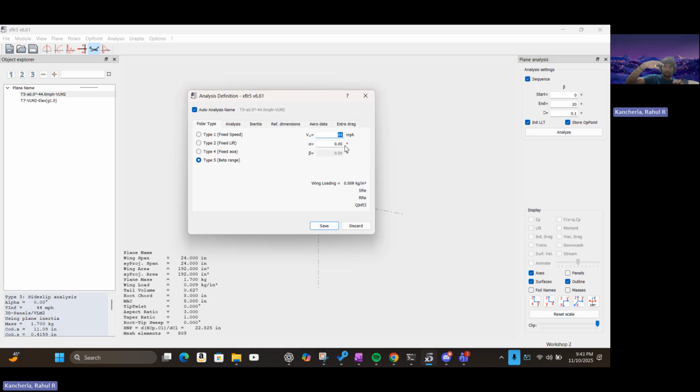And then when you mount the wings onto the fuselage itself, they'll usually have their own little angle. So this particular one is the angle of the wing itself when it is mounted, which should be close to zero. Sometimes people do 2, 3 degrees up or down. But if you're just doing a basic analysis, zero should be enough.